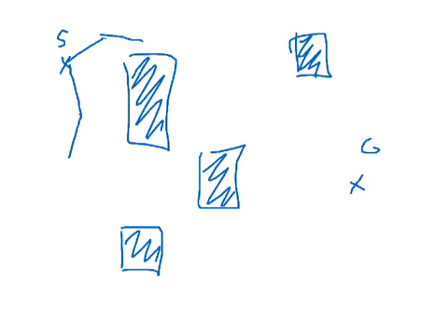Obviously, it would be much more helpful if we would start from the goal as well in the same fashion. So now every time we add something to the start or to the goal, we can look whether we can connect the two trees somehow. If we do this, we will eventually come to a point where it is easy to connect the trees, such as this one where there is a line of sight connection, and we found a path. This approach is known as bidirectional search.